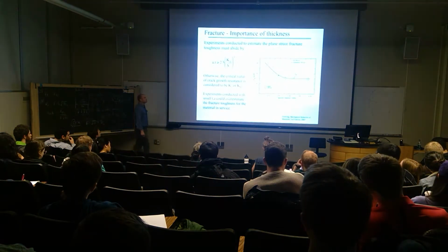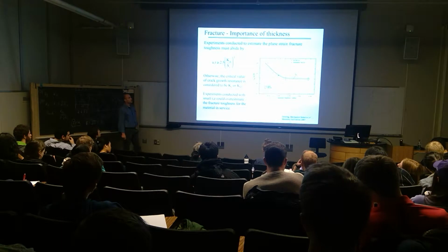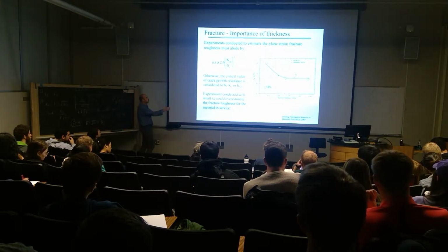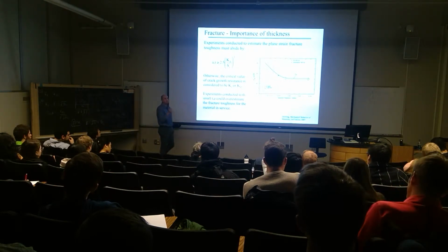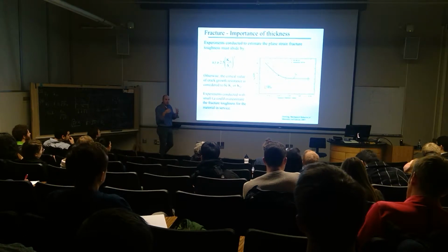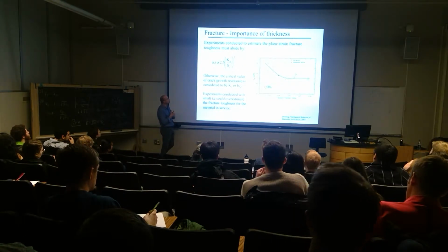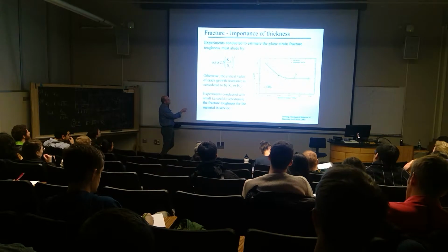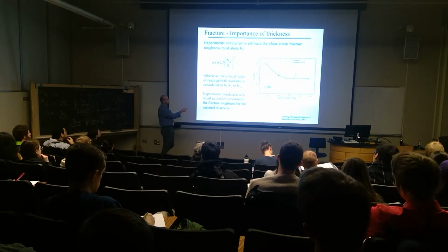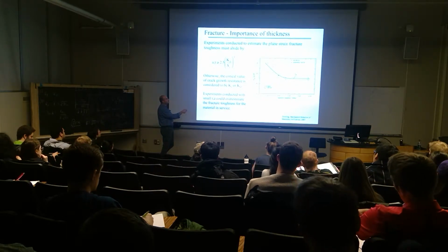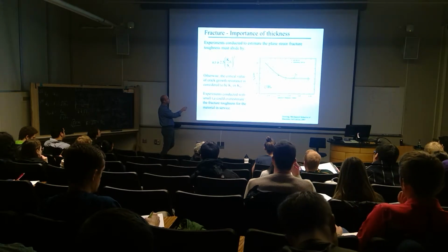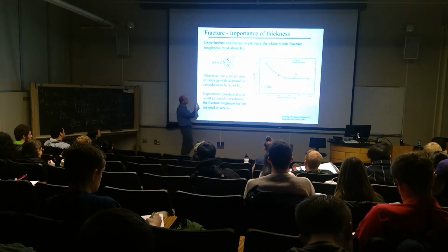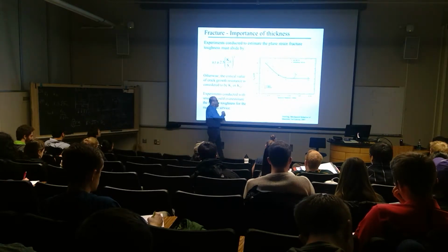So when you look at structures and you look at the way that they evaluate fracture toughness for them, there's some conditions on crack length and thickness of the body that are required to make sure that you evaluate the resistance to fracture in the plane strain conditions. And this is it, that if you know the apparent fracture toughness for that material, and you know the yield strength, then you must have a crack length that's greater than this estimate, and a thickness of the body, that means in the Z direction, that's greater than that quantity as well.